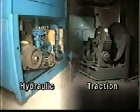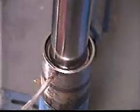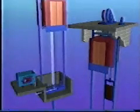There are two types of elevators, hydraulic and traction. Hydraulic elevators usually serve up to 8 floors or stops and travel at speeds less than 200 feet per minute. Traction elevators are designed for taller buildings and can travel at much higher speeds. Hydraulic elevators are pushed up from underneath, while traction elevators are pulled up from above.